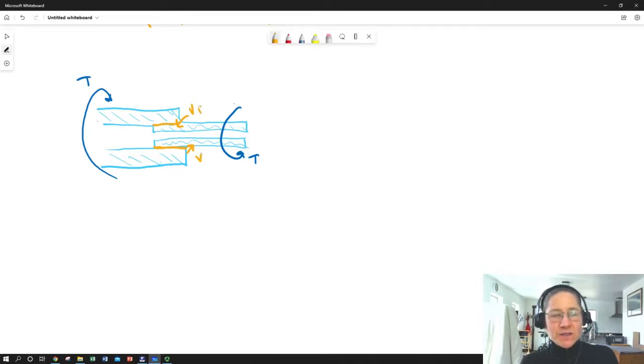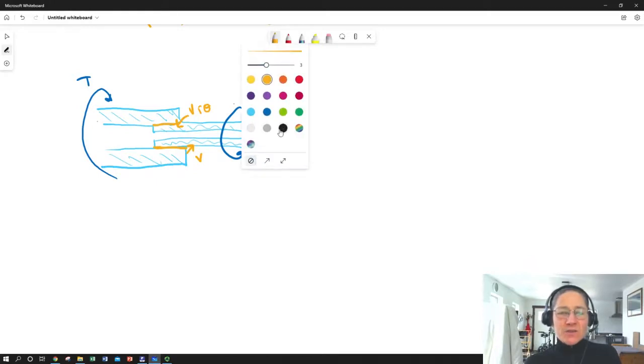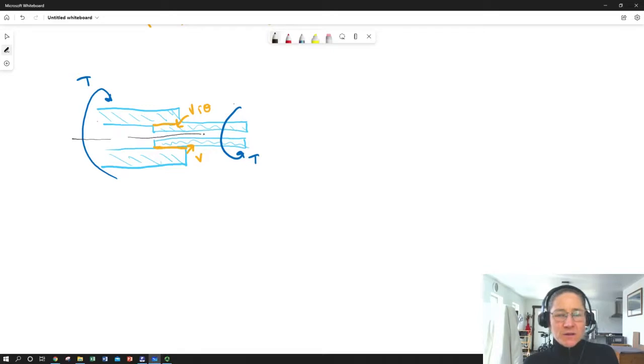So it's on the R surface, and it's going in the theta direction. On this section, it's like it's coming straight out of the board and into the board at every point along here. If we were going to reference that to the center line of the cylinders, because that adhesive layer is thin, it's all at the same R, the same radius. So we can set the shear force due to the shear stress at a single radius. We don't have to integrate a bit of force due to a bit of shear stress over a range of radii, because the same R applies to the entire thickness of the adhesive bond. It isn't very thick radially. It has a very small dr, so we're going to assume it's all the same. So we're making another one of those small angle assumptions.